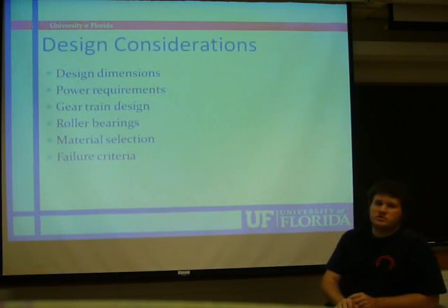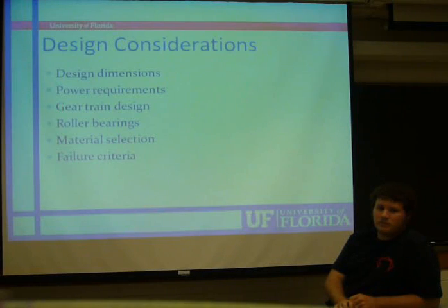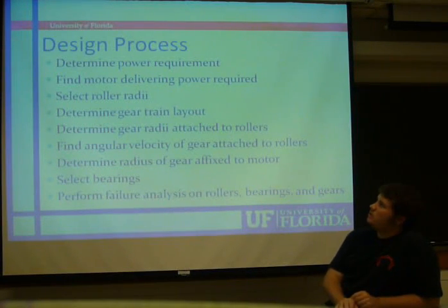Some of the design considerations we took into account were design dimensions, power requirements, gear train design, roller bearings, material selection, and failure criteria. Design approach: we first determined our power, selected the motor, selected roller radii, gear train layout, and angular velocity to match up proper torque required. We also selected bearings, and then overall we performed failure analysis on rollers, bearings, and gears.